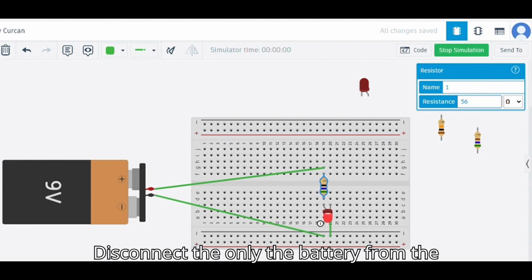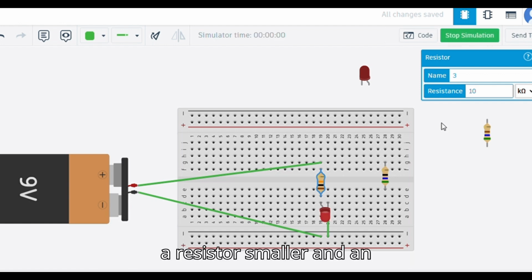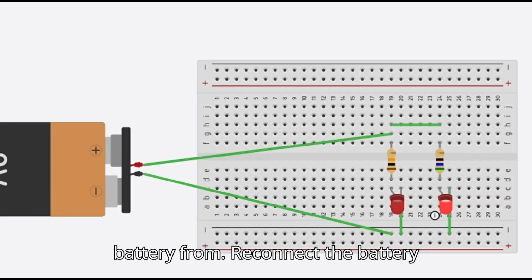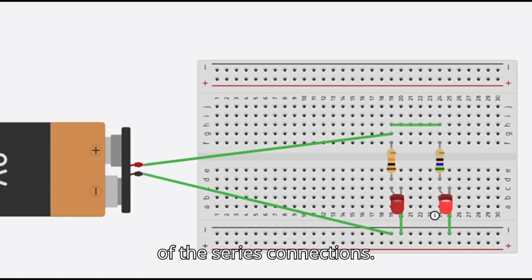Disconnect the battery from the larger resistor series circuit. Reconnect a resistor, the smaller one, and an LED in series. Connect this series connection in parallel with the series connection that you just disconnected the battery from. Reconnect the battery in parallel with the parallel connection of the series connections.